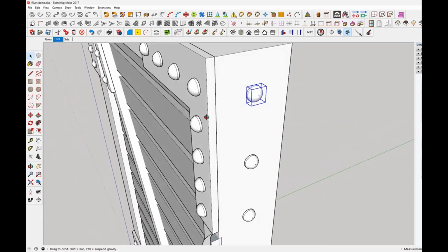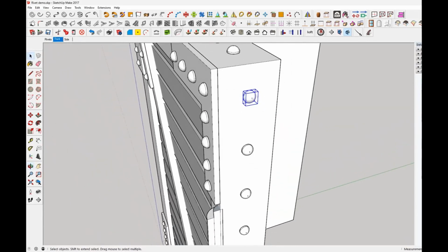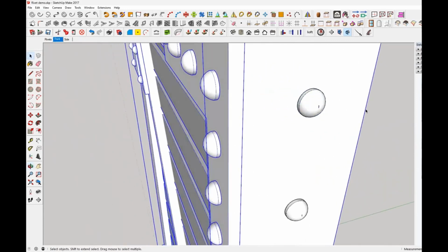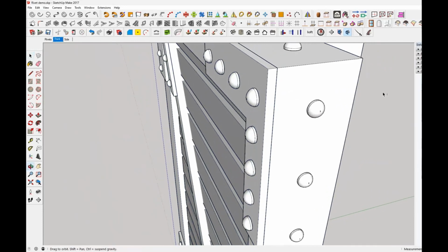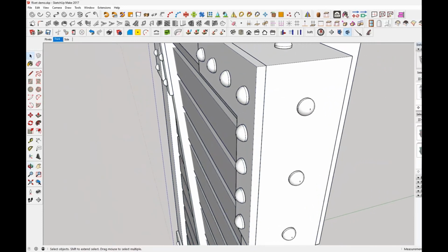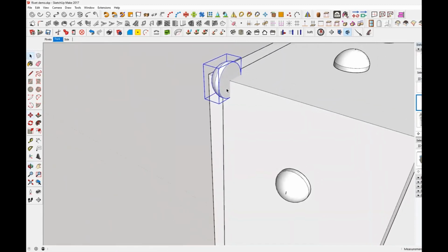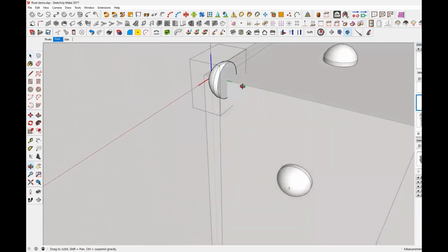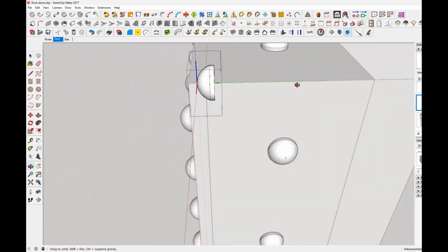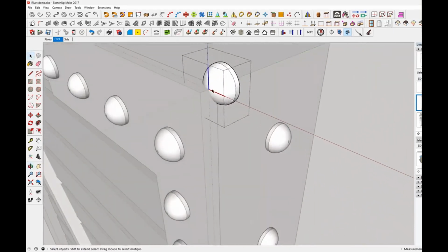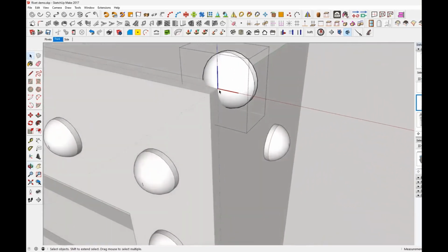First thing we need to do is, because these rivets are components, whatever we change on one, we change on them all. So let's click away, we'll go to the component list and we'll come down. Let's make that a little bit bigger. Rivet, and this is the rivet we've got. So if we put it up here, and then I've actually altered this, but if you double click, actually I haven't altered it, you'll find that the axis is on this one, it's on the front.